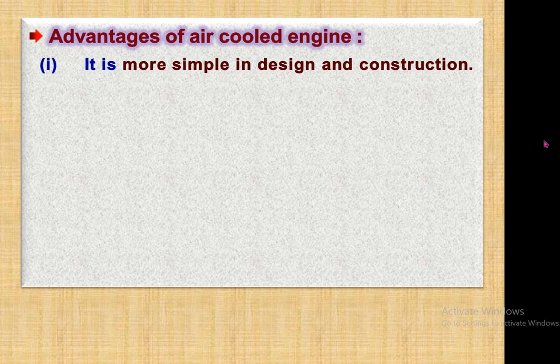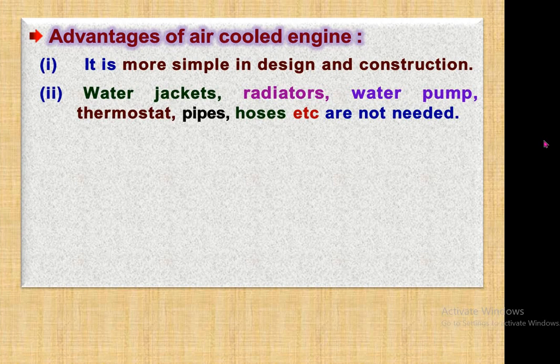Now, the advantages of the air cooling system or air cooling engine. Certain advantages of air cooling systems are there. It is more simple in design and construction. Means there are no extra parts in this system, so it is very simple in construction, and the design is also simple. Water jackets, radiators, water pump, thermostat, pipes, hoses, etc. are not needed.